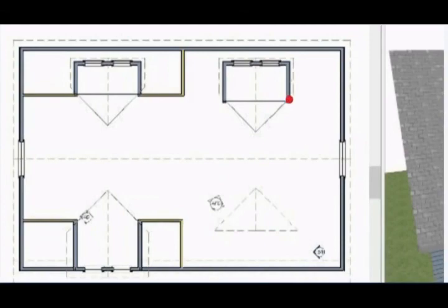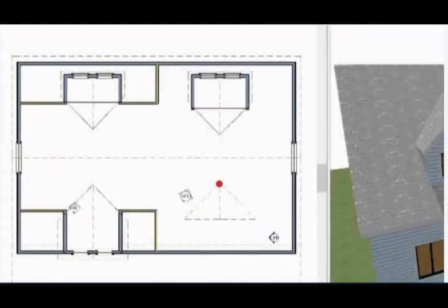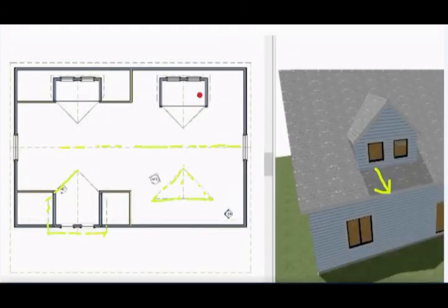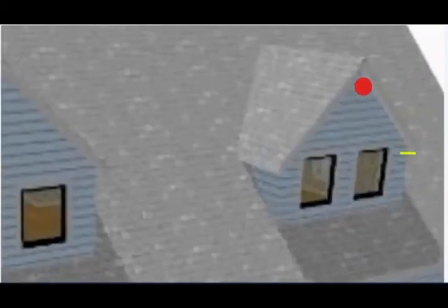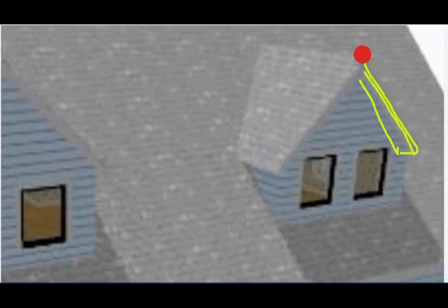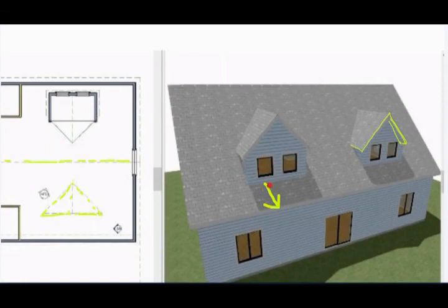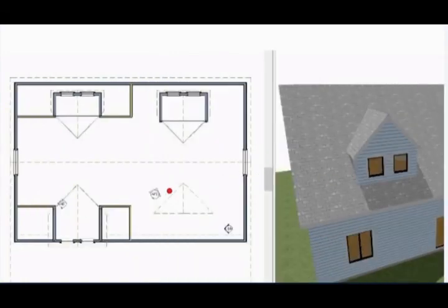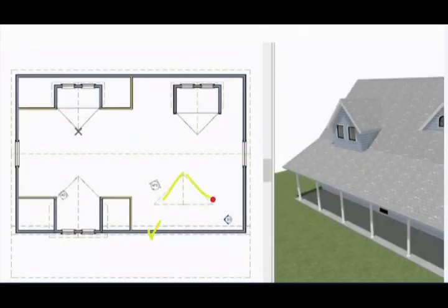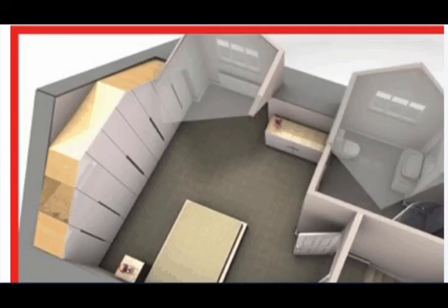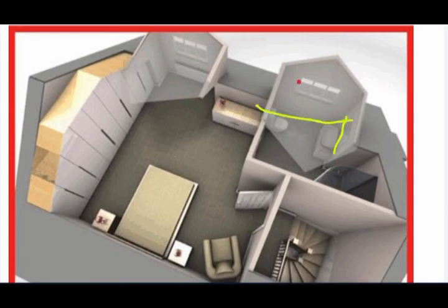Look at here, this is the plan of, let's say, the top floor, but we want to see those dashed lines in your duplex plan, the last floor. So we will understand how the slopes and aims are working with each other. Have you got it? You look at here, it is coming 20 centimeters out of the project, and the reason is that it is 20 centimeters extended in case something happens. So the plan, apart from the duplex floor plan, we want to see the dashed line of the roof in the plan. This is very important. Look at those dormer rooms. You are creating dormer rooms. You are having a setback to have another specific typology.